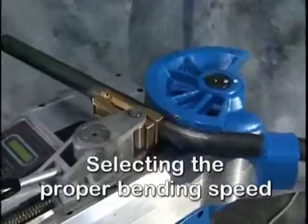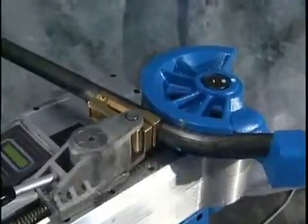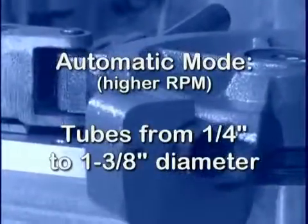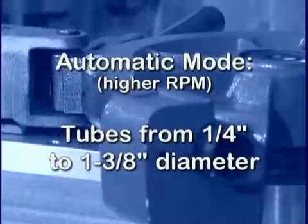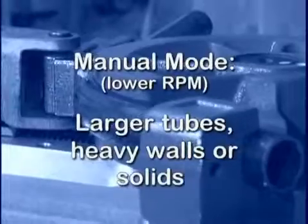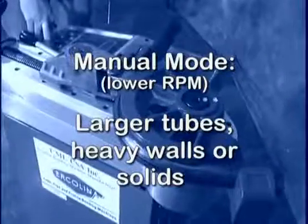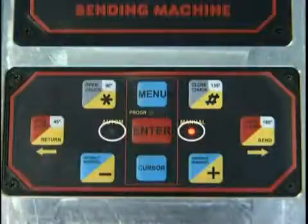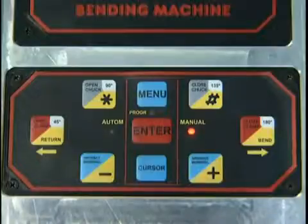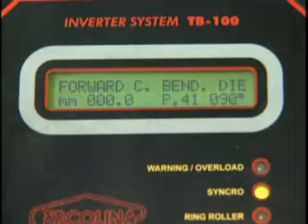Selecting the proper bending speed. The MegaBender 030 offers programmable variable speed bending. As a general rule, tubes from 1/4 inch to 1 3/8 inches in diameter can be bent in the automatic mode at higher RPM. Larger tubes, heavy walls, or solid should be bent in the manual mode using lower RPM. The control panel LED will indicate the current mode of speed control. Should the machine overload while bending, reduce the RPM until the bend can be completed.